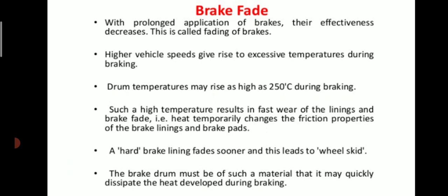That is, heat temporarily changes the friction properties of the brake lining and brake pads. A hard brake lining fades sooner, and this leads to vehicle skid. So the vehicle will skid if the brake fades. The brake drum must be of such material that it may quickly dissipate the heat developed during the braking. So this is the phenomenon of brake fade that occurs during braking.